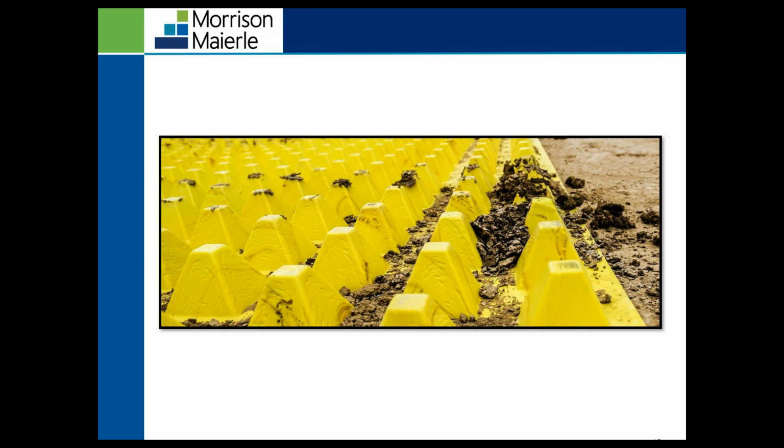Right here, the FOD, it's a track out device. This is something I learned about probably a year and a half ago that contractors are using around here. It's a really hard plastic. Those ridges, those pyramids right there, create depressions in the tire, and it removes a lot of sediment. It's a FODS, and it's a commercial product that you can purchase.